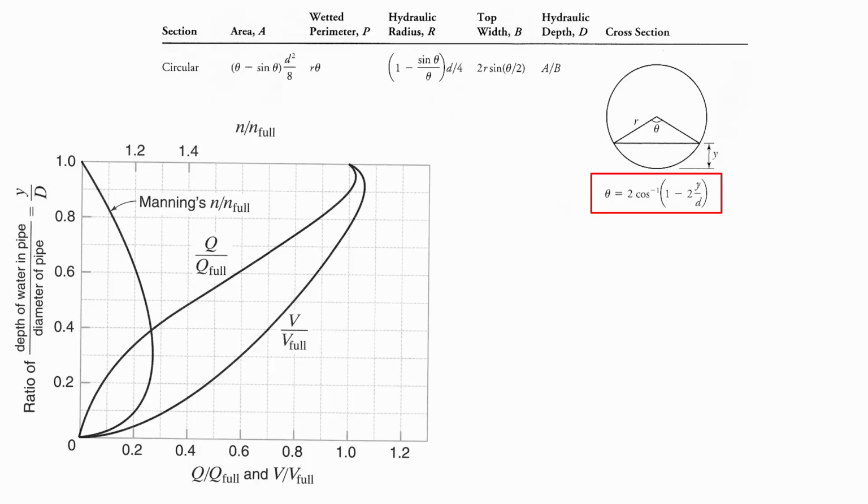And so it's a circular pipe, and so there are some nonlinearities here, and that's what we can see from the curve. There's a similar expression of the velocity of flow compared to the velocity when the pipe is full, and that's related to how much of the flow area is away from one of these frictional surfaces to give you the average velocity.